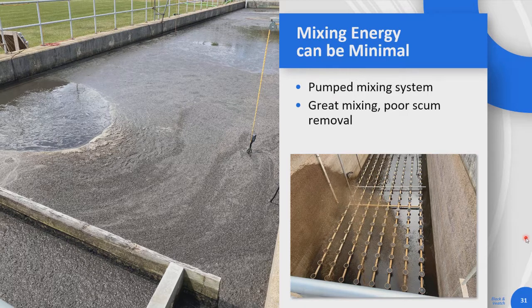And so this was an example in Wisconsin where they were able to repurpose a tank. They just put in a few submersible pumps, kind of a header on the RAS discharge, and it gives enough mixing where you do TSS profiles and it's essentially mixed. The one challenge, and I'll show this on a couple facilities with repurposing tankage and reversing the flow, is that you can have scum capture, and it's amazing how much scum can come out of RAS. So for this facility, it's an underflow discharge out of the tank, and it just traps that scum.